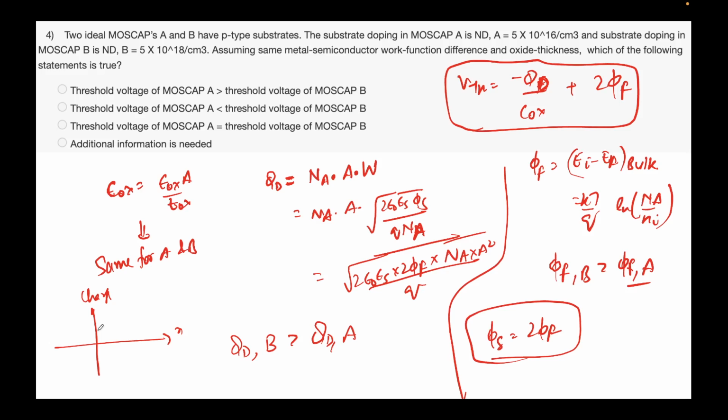Okay, this is the analysis that we had done, because VTH depends on inversion charge, the band bending and the depletion charge. Depletion charge is higher when we have more doping, because you have more to deplete, essentially, as simple as that, right? And your phi f is higher because your band bending is also higher. Now phi f is higher because your Na is high, essentially.